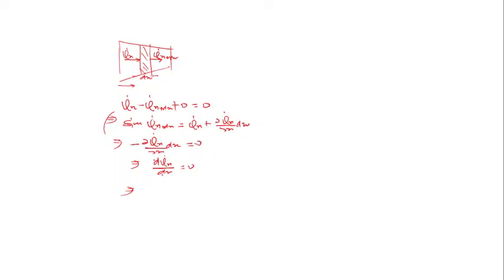Now again, the rate of heat transfer is constant here. In terms of function of x, from Fourier's law, we use minus k A into dT upon dx. Yes or no? Is equal to 0. And this k and this area I can't take outside of this bracket because they are functions of x.